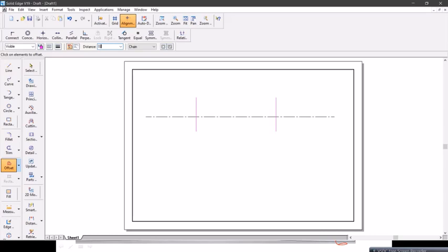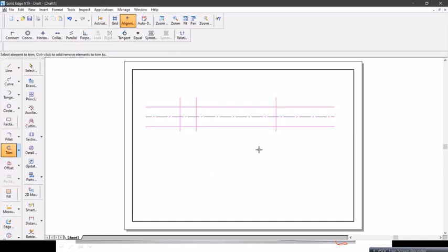Next we'll go for offset. Now what is the relation to calculate the thickness of bolt head? It is 0.8d. Now I'll select it and place it on the left hand side. Now I've made the fixation of boundary. Now I'll go for offset. I'll select 12.5. I'll select this center line, top and down. Now I'll trim unwanted portion here.